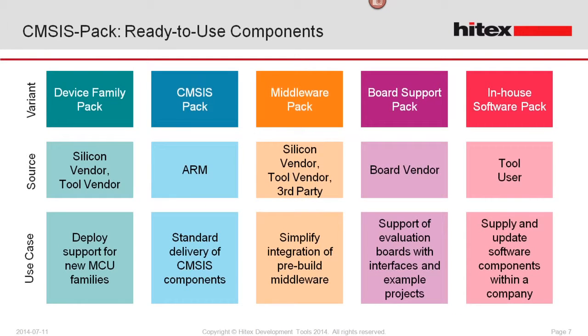So there are a number of use cases for these software packs. Today the most common use is one called a device family pack. So this provides all of the support files for a given family of microcontrollers. So things like the startup code, the header files, flash programming algorithms, documentation, etc. So when you want to work with a particular family of microcontrollers, you can download and install its device family pack, and then you have everything that you need.